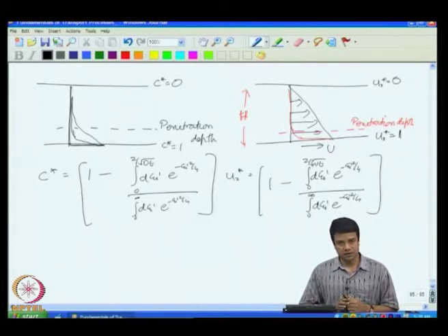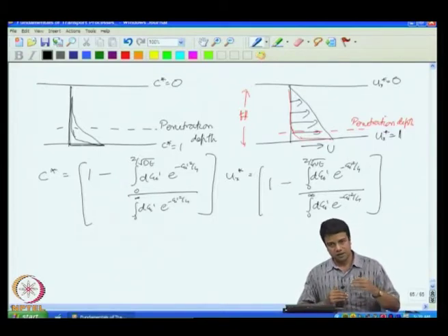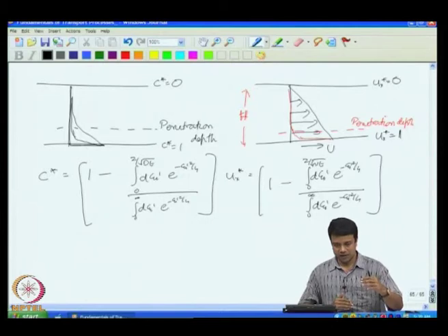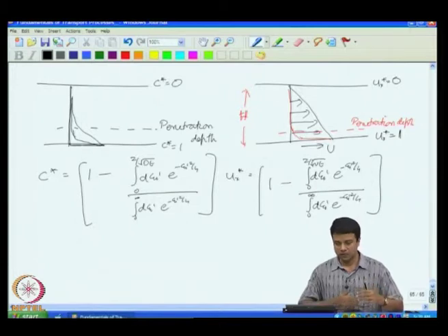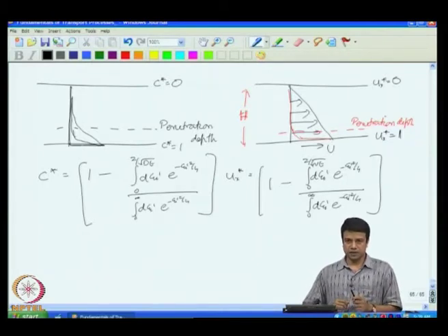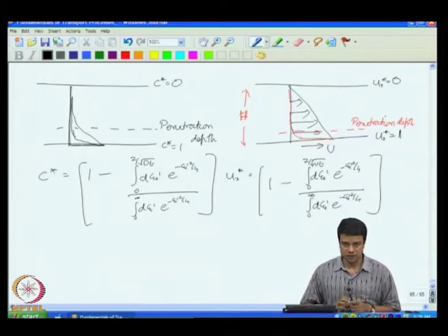These are semi infinite domains where you have one surface and an infinite fluid on top, and either the concentration, temperature or the velocity of the bottom surface is instantaneously changed, and then you find the diffusion going upwards. So, we do that by the similarity transform. In this case, it was a dimensional necessity. The fact that there is only one dimensionless group was a dimensional necessity.